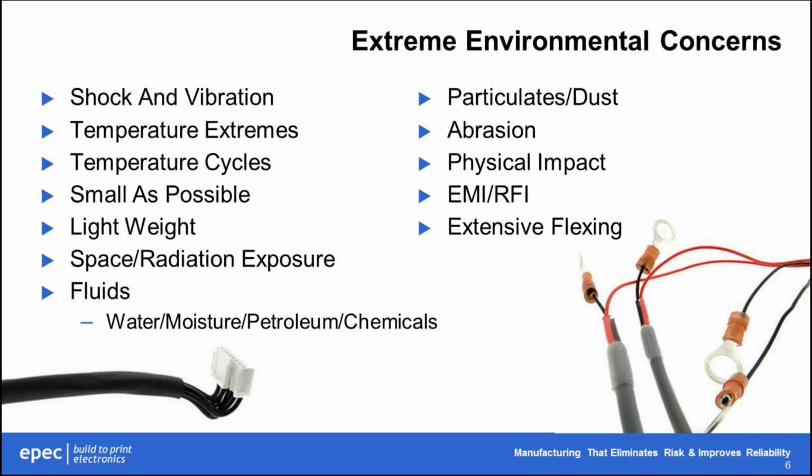If we look at an assembly designed for use in a medical environment, for instance, it can be exposed to repeated sterilization using steam and pressure and high heat. The materials used in the design of that assembly need to be able to withstand those conditions, and the design needs to be moisture tight and protect the termination points and any electronics included within it.